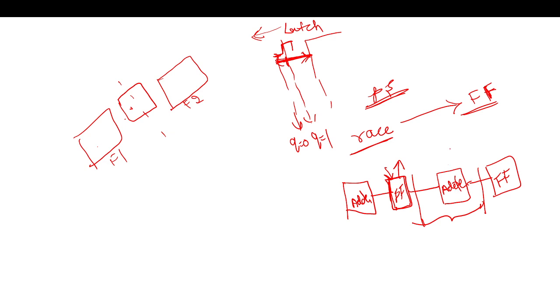For testing, I connect the flip-flops in a chain fashion and add some multiplexer logic to enable this chain operation only during testing. At that time, I need only one shift in one clock cycle, observing the flip-flop output at the final output.